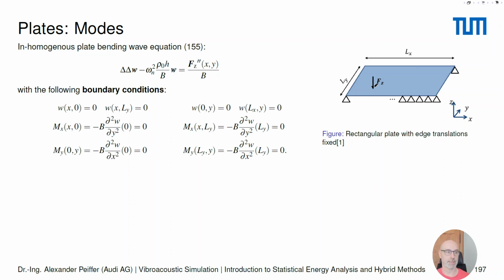In our modal test case, we take quite practical boundary conditions, so the translations are fixed around the edges, and there is no moment applied. So we say that they are translationally fixed and rotationally free.